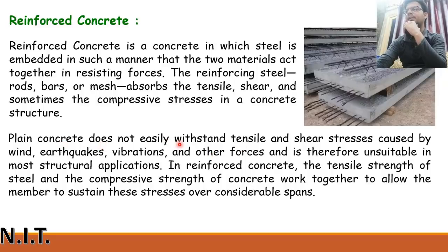So plain concrete does not easily withstand tensile and shear stresses caused by wind, earthquakes, vibrations and other forces, and is therefore unsuitable in most structural applications. Vibrations can be machinery vibrations. In reinforced concrete, the tensile strength of steel and the compressive strength of concrete work together to allow the member to sustain these stresses over considerable spans.